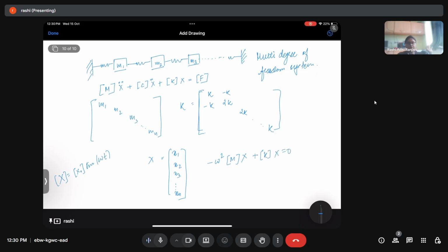We are for now not considering forcing and damping because when we want to find out the natural frequencies or the modal frequencies, we don't have to consider the damping or forcing because it does not depend upon the damping and forcing. Mind you, it is only for the linear system. When we talk about a nonlinear system, the resonant frequency is even going to change with initial condition. Forget about the parameters. You think even the initial condition is going to change the resonance frequency, the harmonic frequency. So parameters, definitely it is going to affect. This is only for the case of linear system.